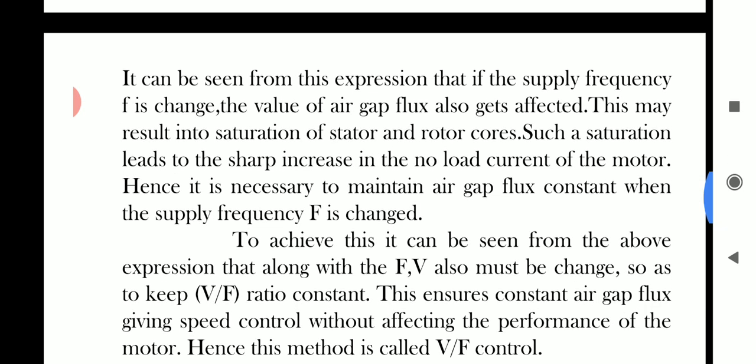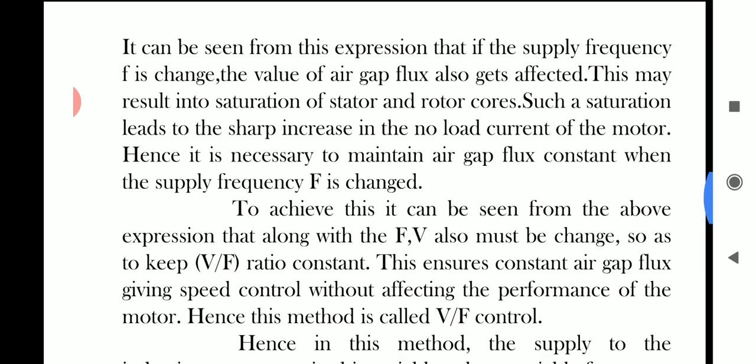This may result in saturation of the stator and rotor core. Such a saturation leads to a sharp increase in the no load current of the motor. If you are changing the value of the frequency continuously, then your flux gets affected. If the flux gets affected, then the magnetic condition of the motor gets disturbed, and that leads to saturation of the stator and rotor core. So what will happen if the saturation occurs in the stator and rotor cores? That will lead to a sharp increase in the value of the no load current.